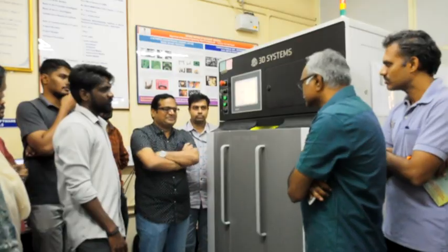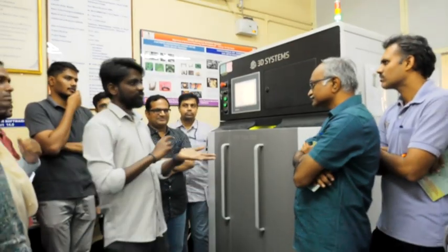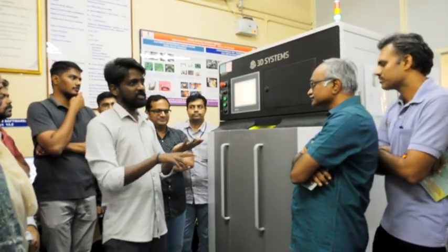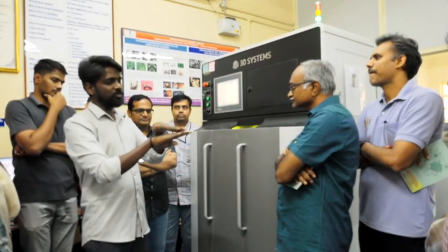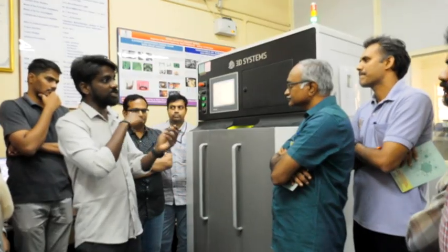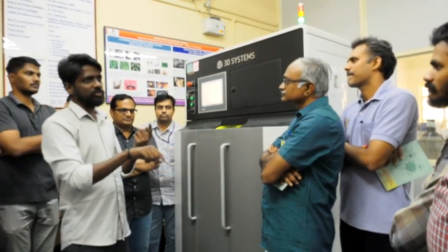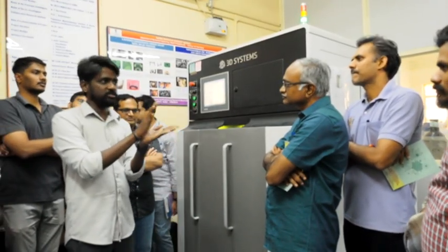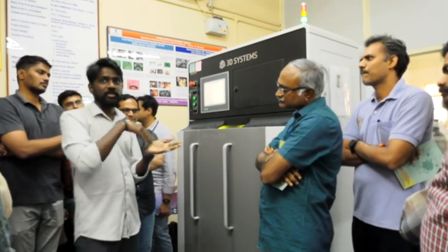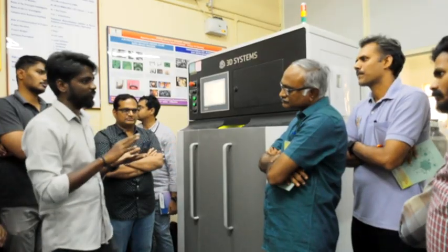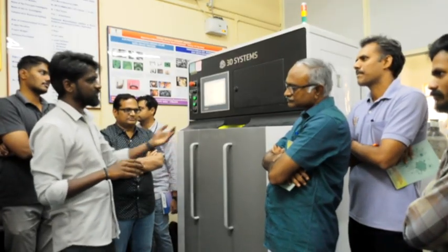Exactly, yeah. So before that, we have to do some remelting of the initial layers. Why? Because the substrate will be the same material, right? They have to attach to the substrate. That's why we are doing double remelting. Or else, if we do single melting, it will get distorted. So in order to reduce that, for the initial 5 to 10 layers, double sinter will be preferable. We are following the same pattern here.